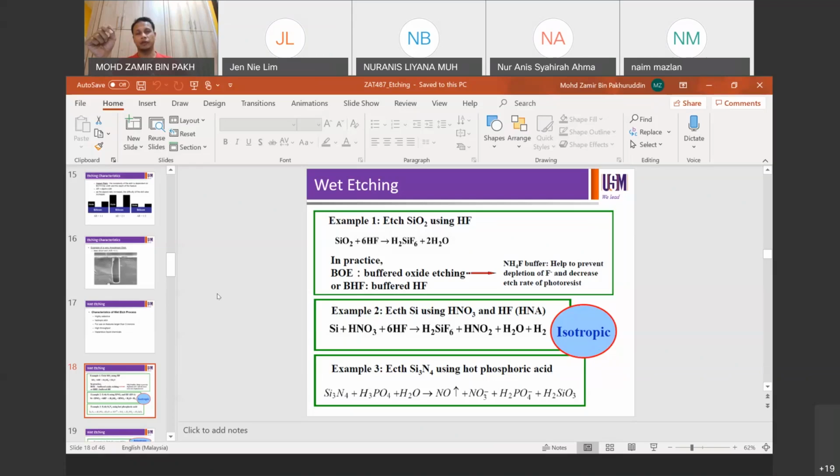Hydrophilic means the water will stick on the surface of the wafer. That means if your surface is hydrophilic, with water sticking to it, you still have your native oxide on the silicon. It's not completely removed yet. We learned hydrophilic and hydrophobic in secondary school, right?